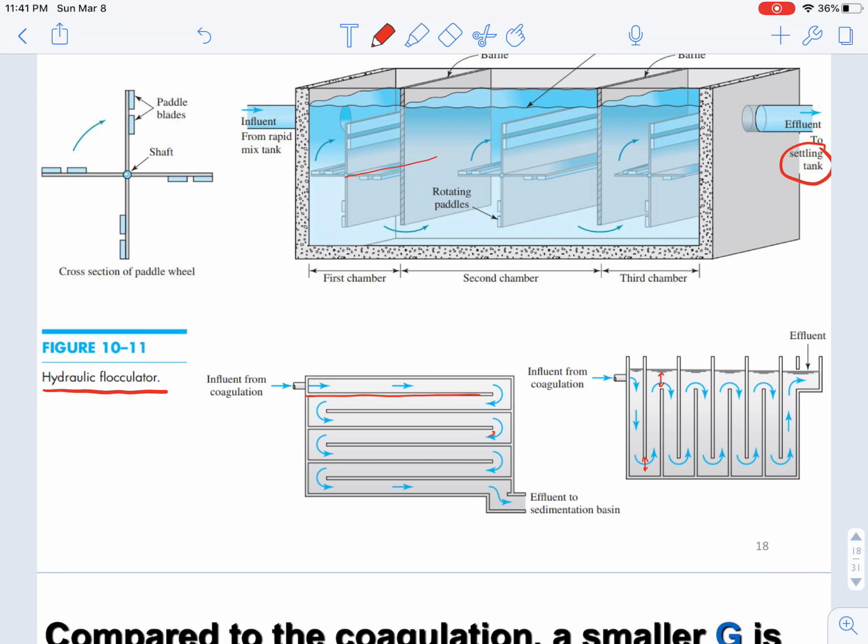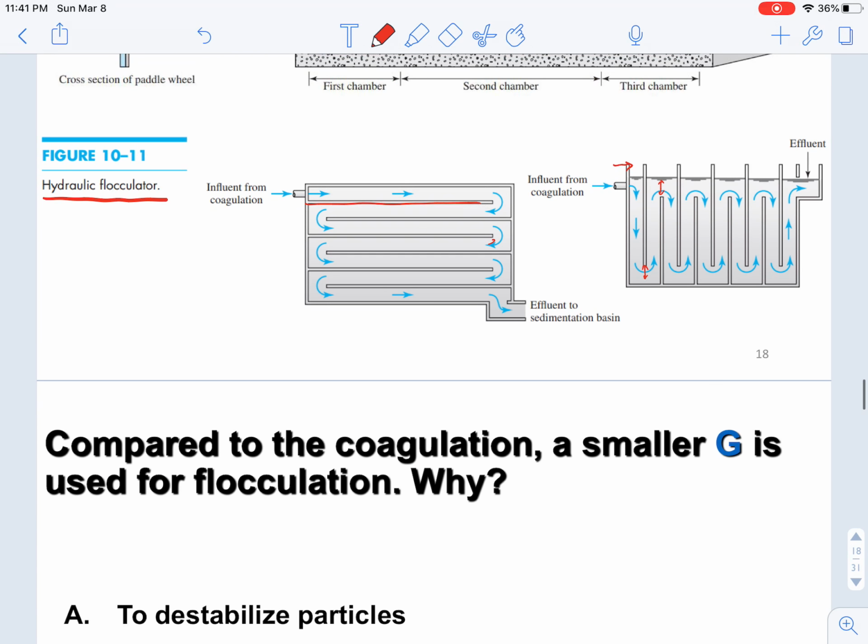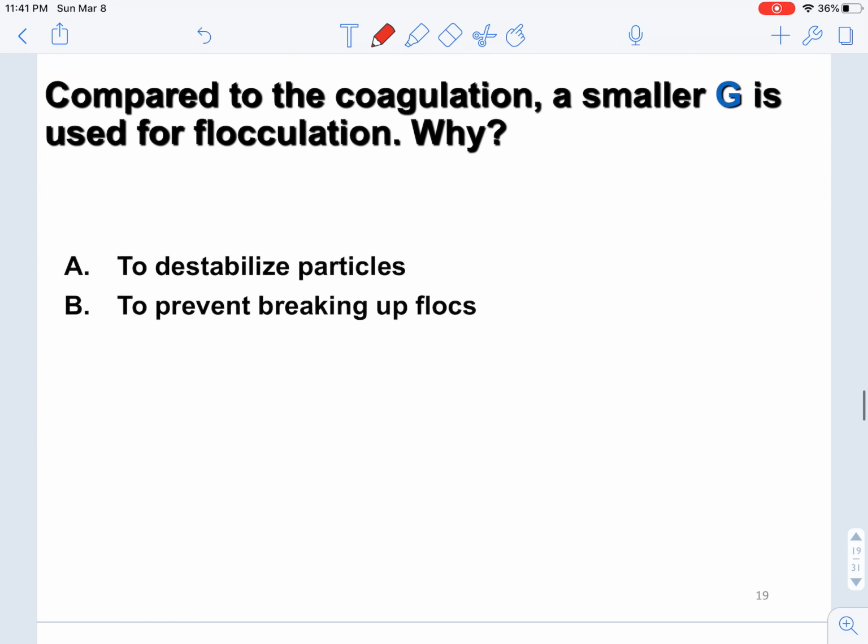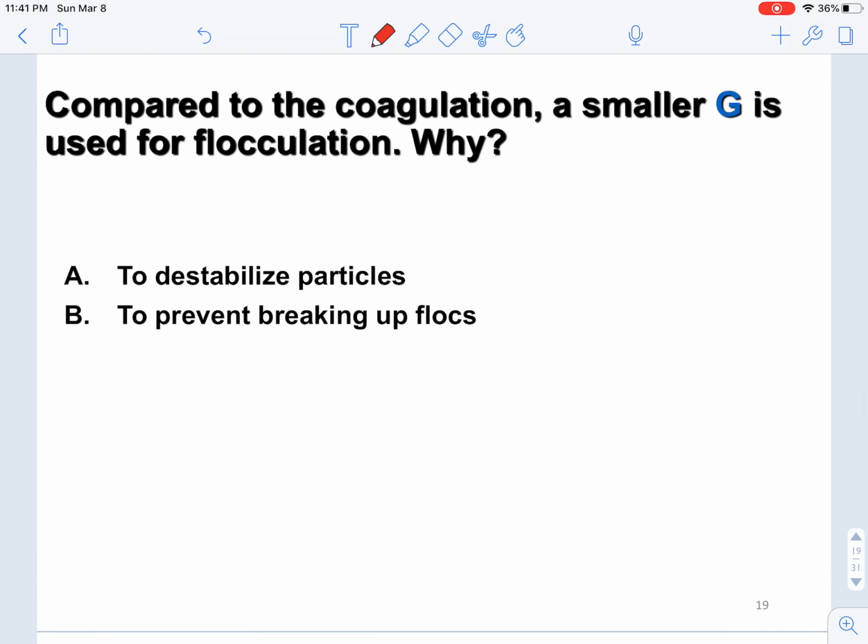So this guarantees that when the water is first introduced into the chamber here, it will first flow to the bottom, and then it's going to go back this way, that way, this way. This will guarantee that the water will get further cleaned up, or have a longer retention time in this reactor here.